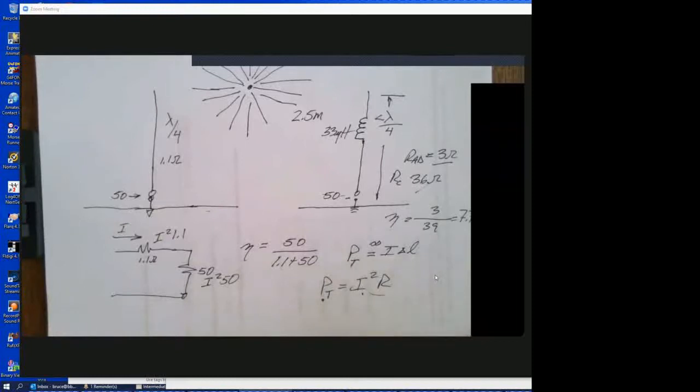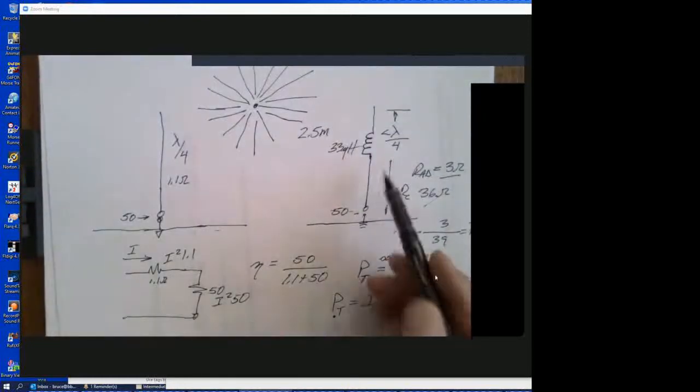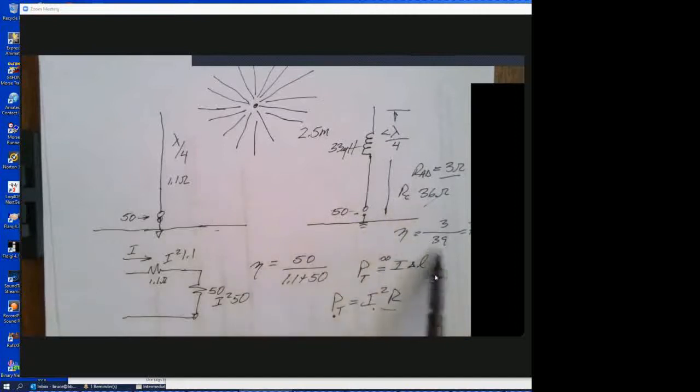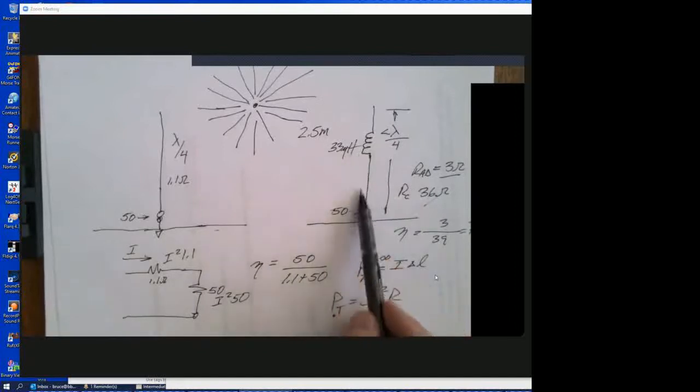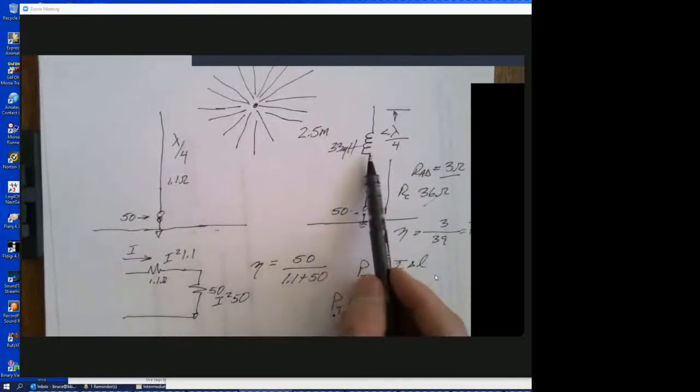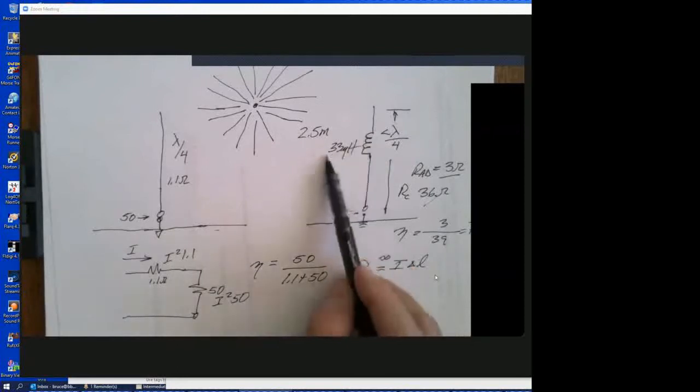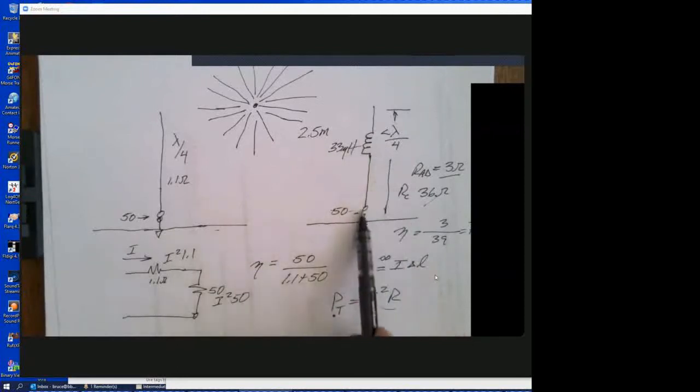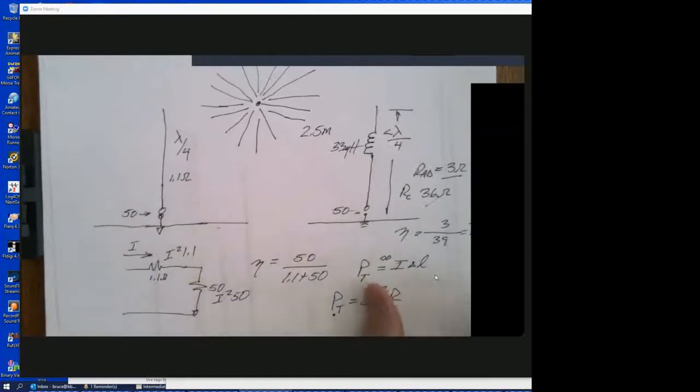So I'm watching my time here. I want to talk a little bit about some various antennas that we're using, and in the interest of time, I've already talked about the short antenna. With the short antenna, you're sacrificing your efficiency to get the size, and you must have a good ground with it. Let's say you're using a vertical, or even a dipole, these coils will be in series. You're basically having two verticals side by side, and so therefore the efficiency will still be low.